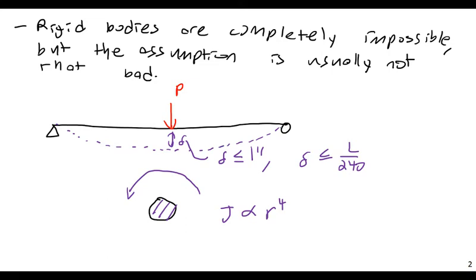That makes sense, right? If you spin something, just like a pizza, if you imagine an Italian chef spinning a pizza in the air and making it expand outward, right? Now the same thing happens for all materials, even aluminum, steel, metals, whatever. As you spin them, they will ever so slightly expand. But usually, if you try to calculate stresses in that material, you may analyze it as a rigid body.